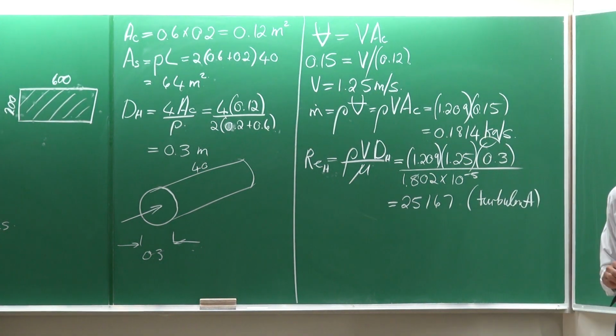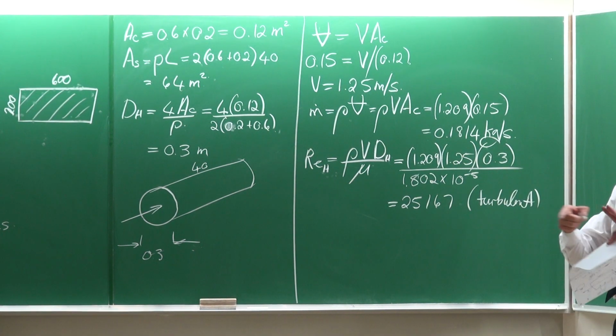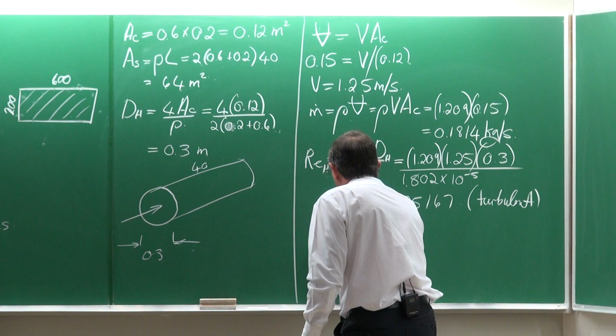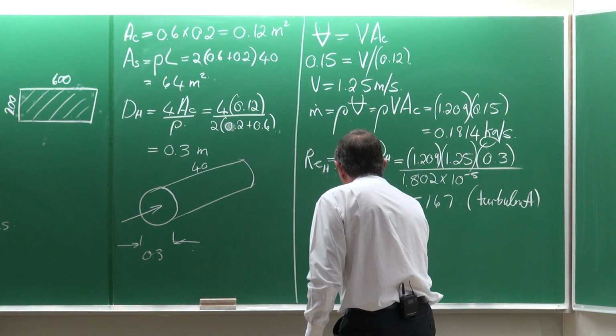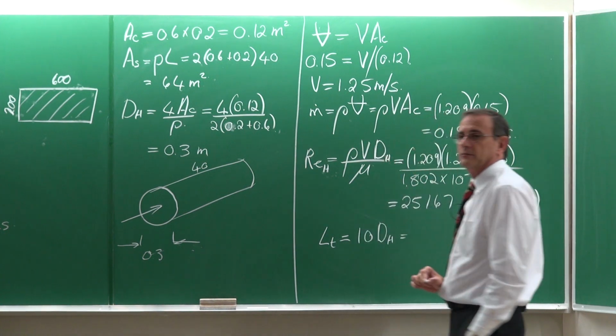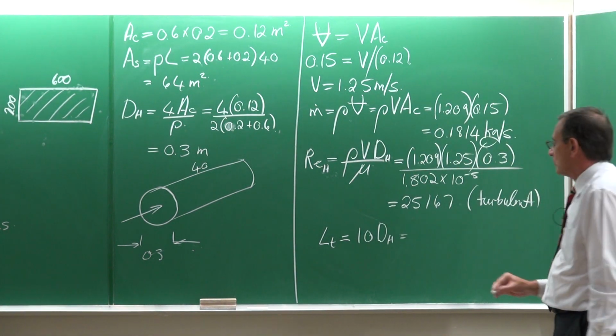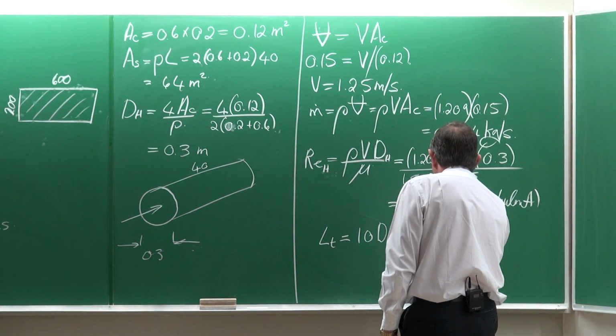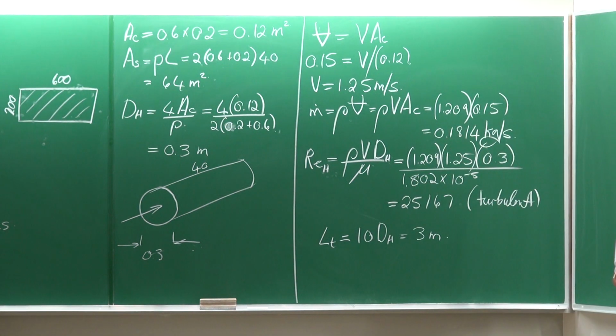Okay, turbulent flow. Therefore, because it's turbulent flow, how long will it take to be fully developed? It would be 10 times the hydraulic diameter. So it is 3 meters that it will take.